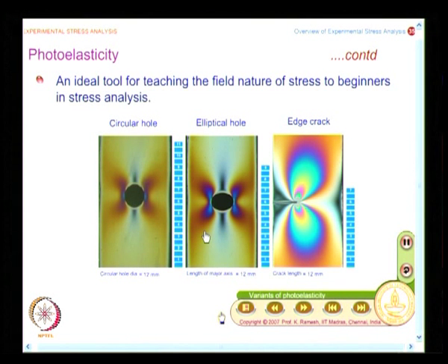and you do not need to explain. You see very few fringes here, slightly more fringes here, and here I have not put the load as 6, I put it as 7; when I put it at 6, you have a large number of fringes here. So, if you have an appreciation of looking at fringe information, the density indirectly indicates the stress levels are high. So, for a beginner, you get the field nature, you understand what is stress concentration,